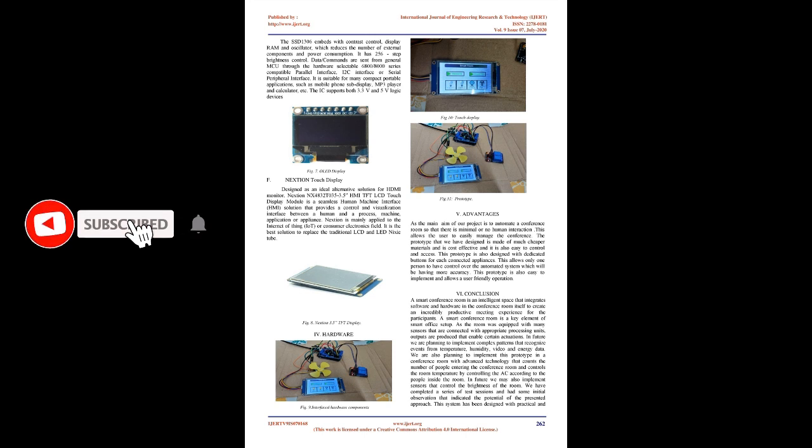C. 5V dual-channel relay. A relay is an electromagnetic switch operated by a relatively small current that can control much larger current. This module is designed for switching two high-powered devices from your Arduino. It has two relays rated up to 10 A per channel at 250 VAC or 30 VDC. There are two LEDs on the relay module indicating the position of the relay. Whenever a relay is activated, the respective LED will light up.